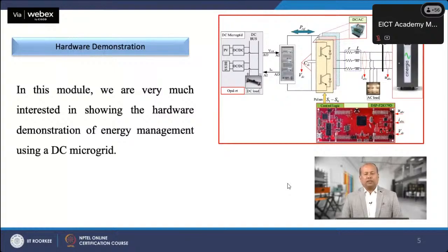This DC bus is connected to the DC input side of the IGBT stack. The AC side of the IGBT stack is connected to the input side of the MCB through an inductor. The output side of the MCB is connected to the grid emulator. The bulb is connected at the MCB point, which acts as a parallel AC load. Most of the components used in this hardware test bed have been explained in the previous module.